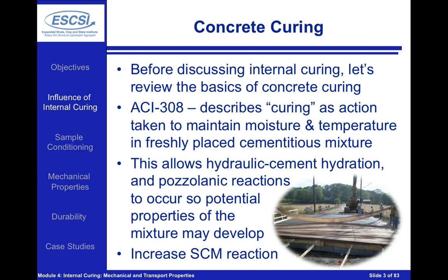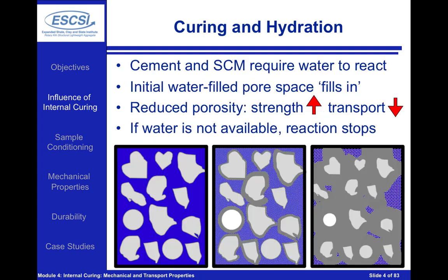We're curing the concrete, and that's going to help to increase the reaction of the Portland cement and the supplementary cementitious materials. Now, the important concept behind this is that cement and supplementary cementitious materials require water to react. If you take water out of the equation, those materials will essentially just sit as dry powders and won't hydrate, they won't react. If we can supply water, those systems will react and will begin to fill in the porosity.